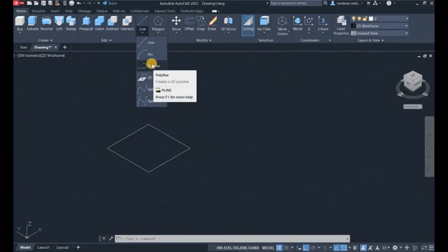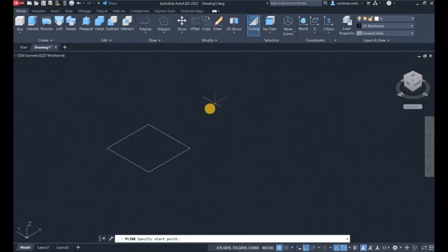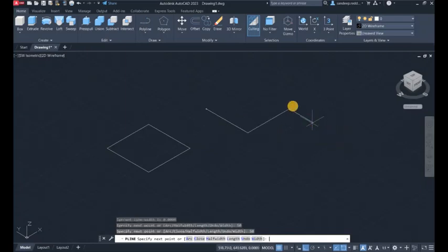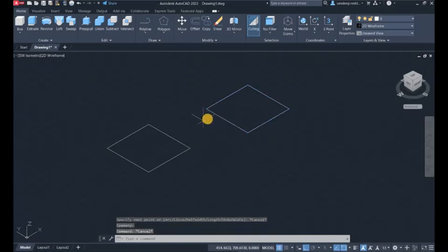And here I have, using the polyline function, drawn the same square with the same dimensions. As you can see, if I move the mouse over that square drawn using polyline, it says it is a polyline. So you see the difference. If I select the square drawn using polylines, that entire square is a 2D object on the right, and on the left is just 4 lines.